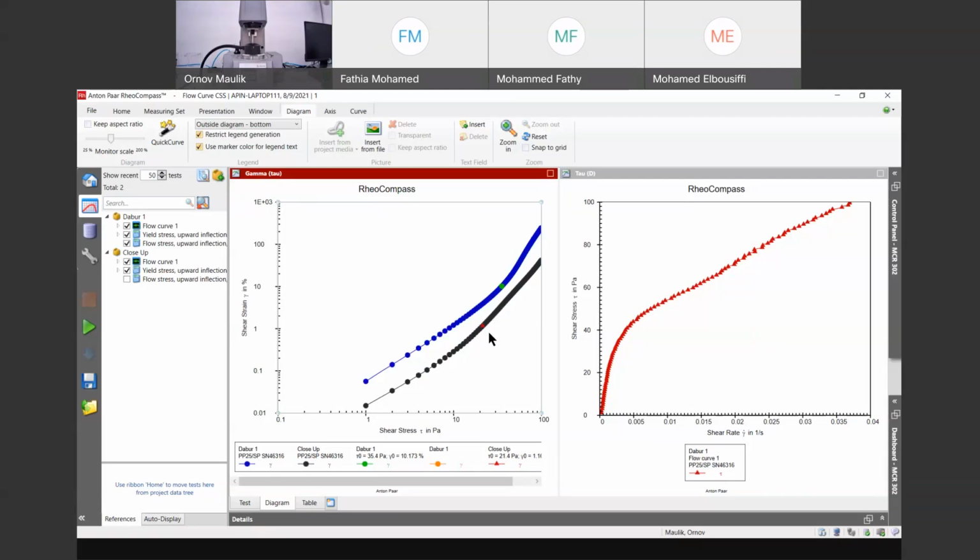or randomness in them, because ideally in a rotational test, what you are doing most of the time is rotating your geometry onto the sample. So even if you are using very low shear rates or very low stress, you don't know whether you are actually breaking or distorting the structure or not, because you don't know the elastic range.